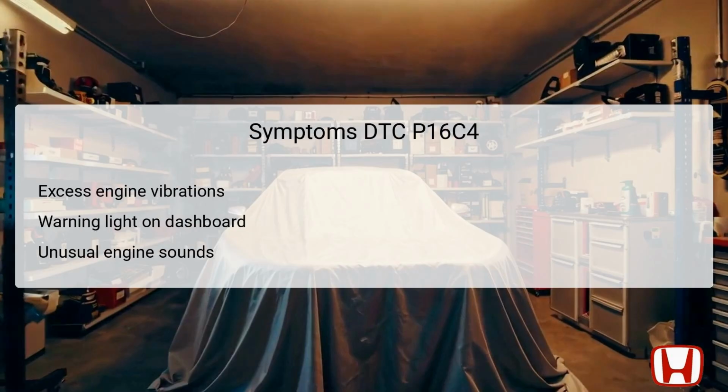The vehicle may exhibit several symptoms that could hint at DTC P16C4. A common symptom is an increase in engine vibrations felt within the cabin, which occurs if the engine mount actuator fails to function correctly. As the active control engine mount struggles to adequately dampen engine movement, drivers will notice more pronounced vibrations, particularly during acceleration or when the vehicle idles.